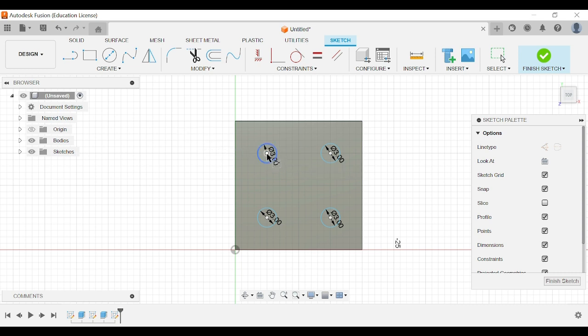And what I can do now is I can press on the center of the circle, and I can press on the outside line here and drag it up. And you can see it's at 5 at the moment, which is good. We want 5, but I'll just type in 5 anyway. It says 5.0000745. I'm just going to type in 5 to make it exactly 5, even though it probably wouldn't matter that much.